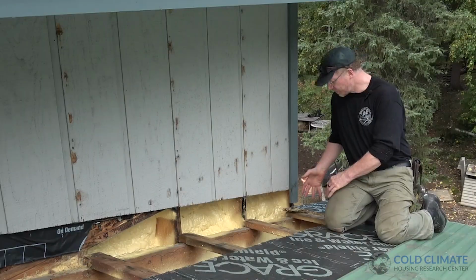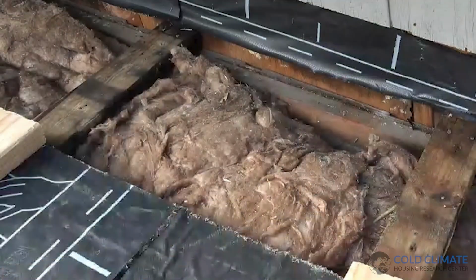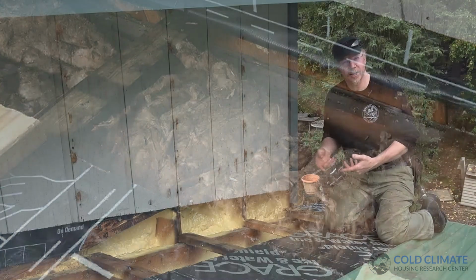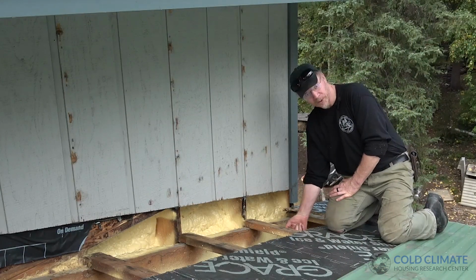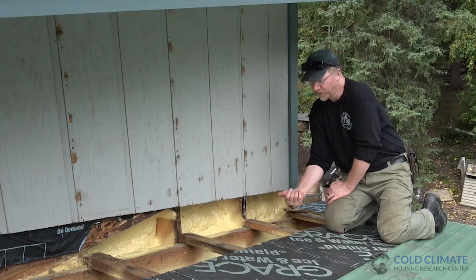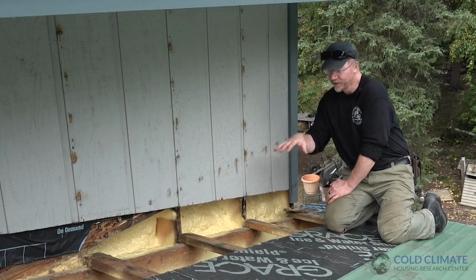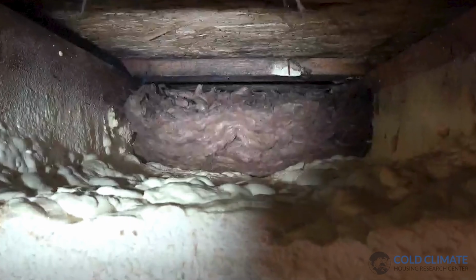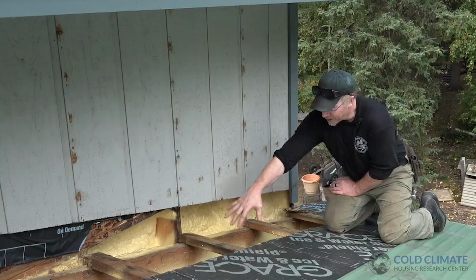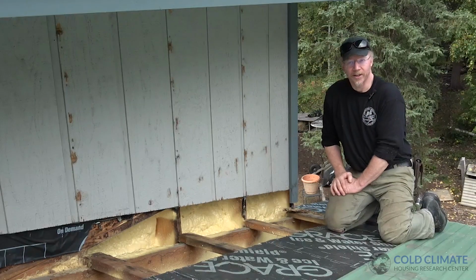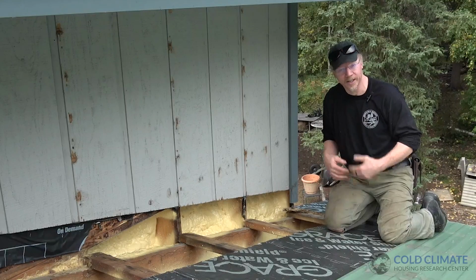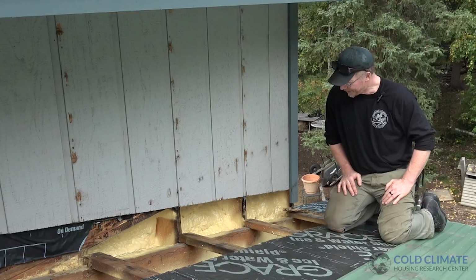We have removed the fiberglass insulation that was in this first rafter bay here, and sure enough, just like we saw from below when we were looking up through the closet opening, which is right below me, the insulation was plugging up the rafter bay. Every single space along here was plugged by fiberglass, so this roof just didn't have a good way to evacuate moisture and condensing and dry out.